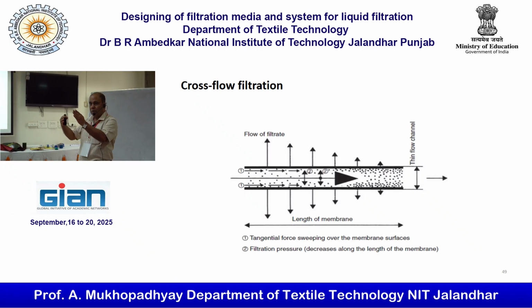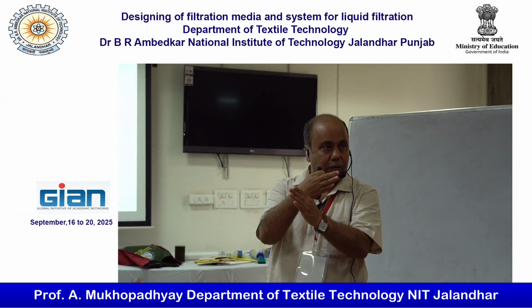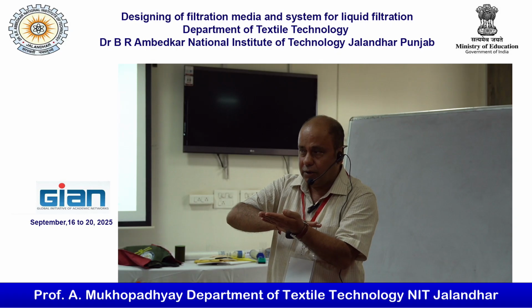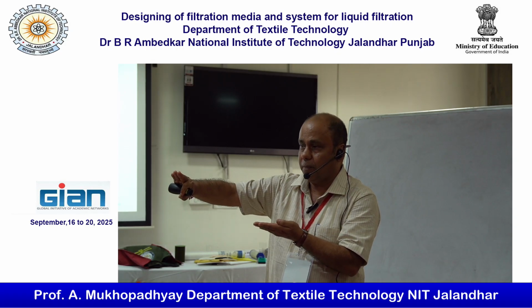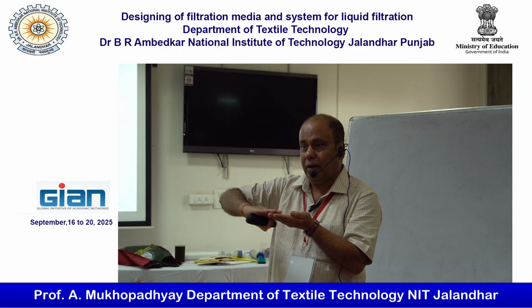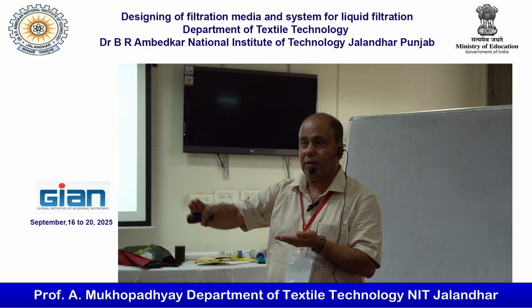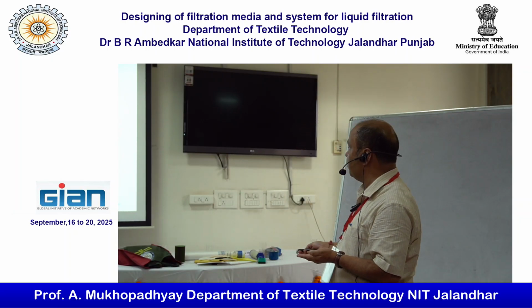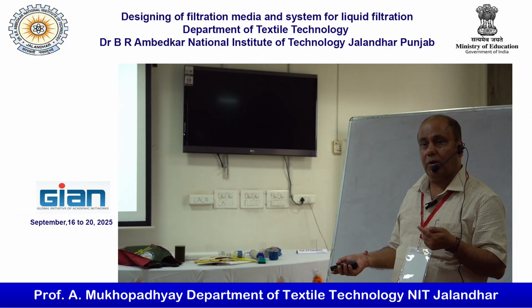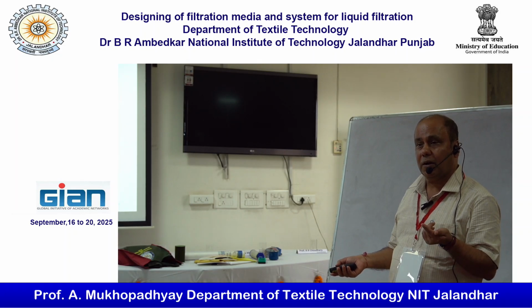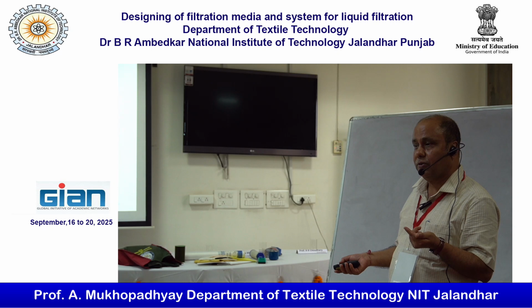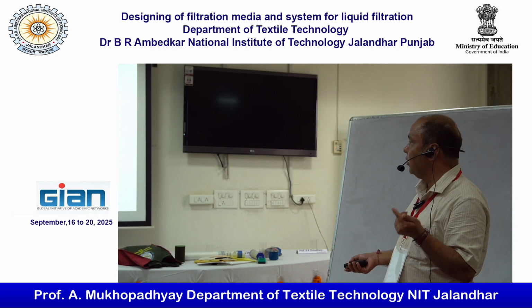Dead end filtration means fluid is flowing perpendicular to the media, and tangential filtration means it is moving along the media. Blood filtration basically comes under cross flow filtration. All ultrafiltration and all membrane functions, like reverse osmosis, basically come under tangential filtration.